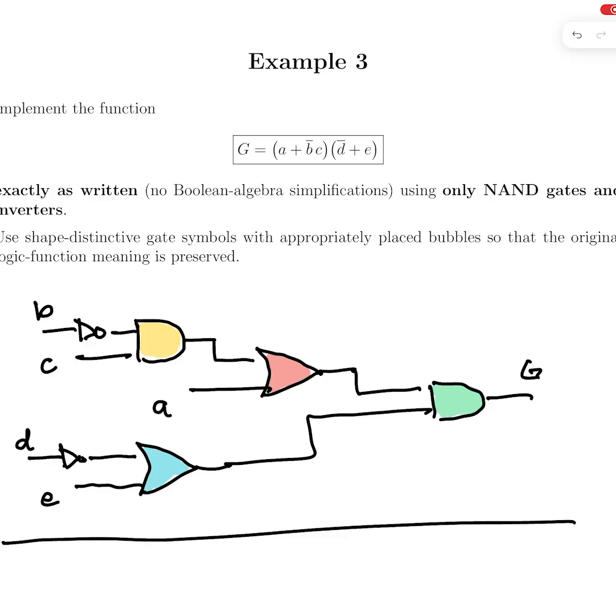So for me, the thought process is to look at the Boolean algebra and form things according to the precedence in Boolean algebra. So I'm thinking here, here's this product term. The first thing I do is I check, here's the product term, and down here, here's the product term. So I need to form that as one of the first things before I get to the OR.